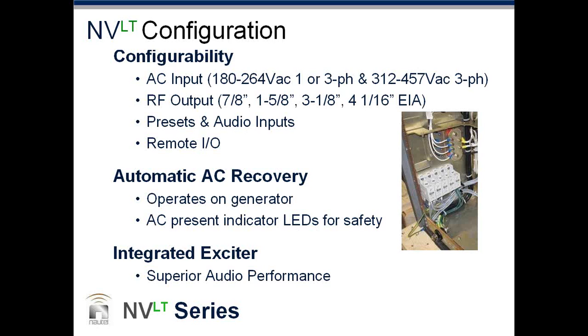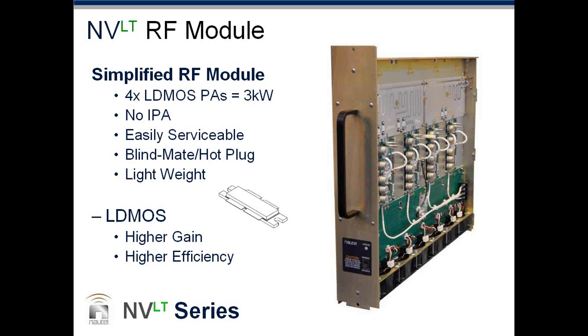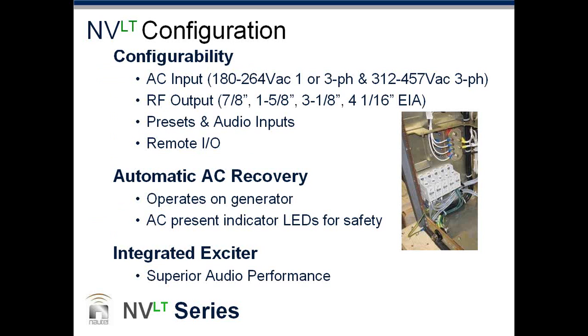Okay. Automatic AC recovery. That's been a long-standing requirement and design criteria for our transmitters. They will obviously go to 0 watts during a brownout or a loss of AC, but they will recover in the exact same mode that they were operating in a very fast manner. Literally a couple seconds. Very good. And then we'll talk more about the integrated exciter and what that provides as well. So this is the new module that we came up with.